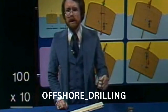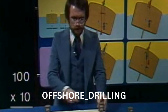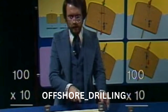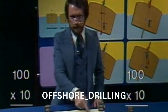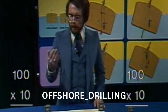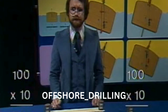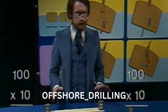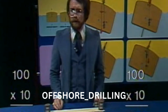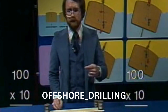We will also place a 100-pound weight on the right side of the fulcrum at a distance of 10 feet from the fulcrum. The moments here are also 100 pounds times 10 feet, or 1,000 foot-pounds. Since the moments on the left are equal to the moments on the right, the seesaw will balance. Okay, now if we increase the weight on the right side of the seesaw, it will be thrown out of balance unless we move that increased weight in the direction of the fulcrum.